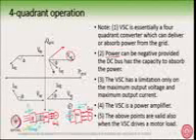Now, the important point here is that the power flow from the grid, or even a motor, so this is not grid alone. Suppose there is a motor here, which is the point I have mentioned in point number 5, and we can discuss it right now. If it is a motor load and the motor has started regenerating: we often run the motor in the motoring mode most of the time, but sometimes we run it in the regeneration mode. Then we allow the inertia of the motor not to be wasted, and we put that energy back into the battery or back into the DC bus.